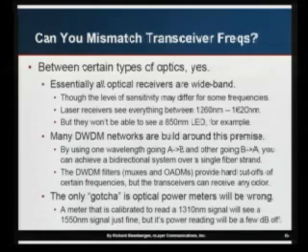So what happens is when you use a power meter, it's calibrated, and there's a button that says 1310, there's a button that says 1550. What that's doing is it's changing the internal calibration. So if it sees light and you're telling it that the light it's going to see is 1310, it might tell you that it's a minus 15. And if the light that it's actually receiving is a 1550, it might actually be a minus 14. And so if you're using integrated DOM, things like that, the value is going to be slightly off. And it's not off by a lot, but it's off by a little bit, just because it's expecting to see 1310 and it's actually receiving 1550. It still sees the signal just fine.